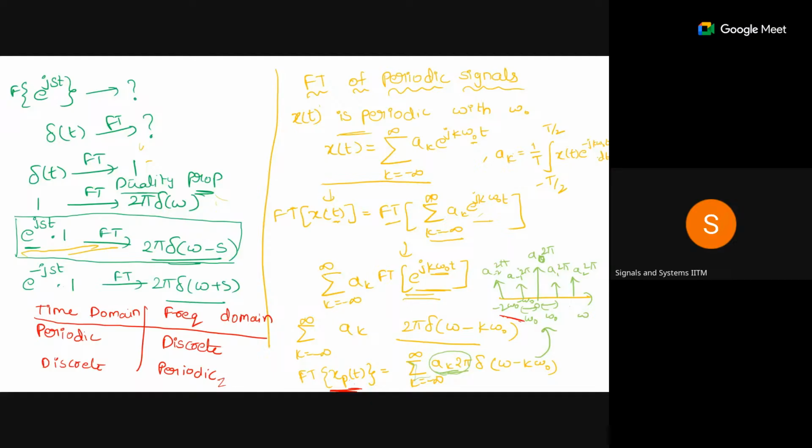And if we use filters, the signal will be attenuated at high frequency. A low pass filter will pass the low frequency signal, and it will attenuate and stop the high frequency, right? This analysis can be done nicely in the frequency domain. In the time domain, we can't do all these things, like finding what the frequencies are. That's why we go into the frequency domain.